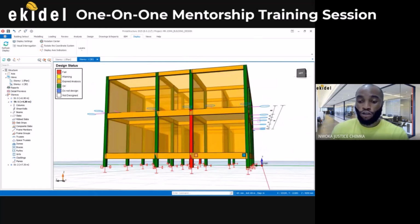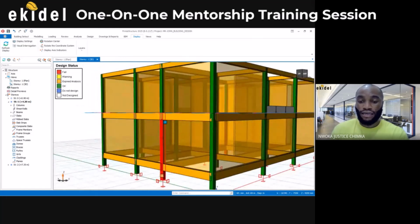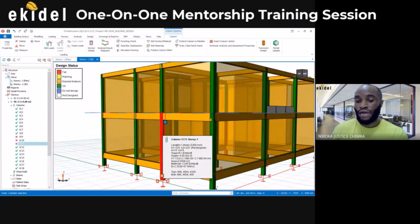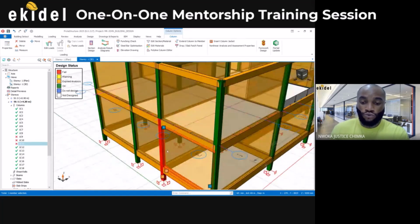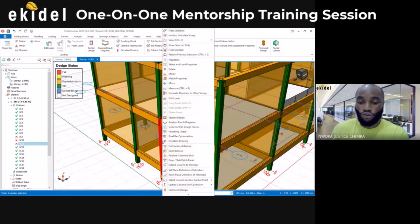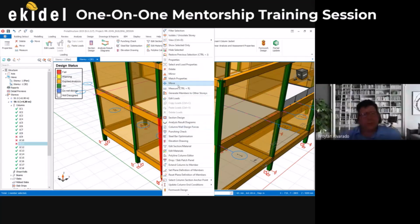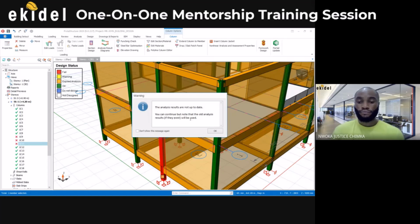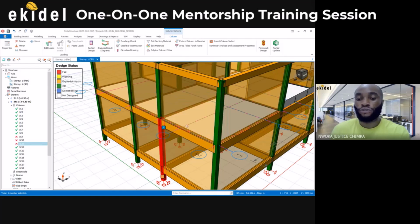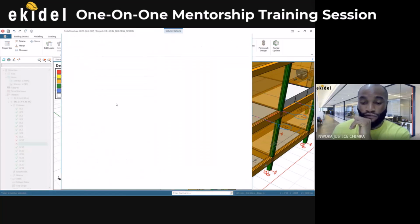But if I touch this column again and increase the size or something, then say okay, let's do it now. For the column, it's the same thing. Click on the column that is failing, right click, and then say section design. Yeah, right here. I'll just say okay, because the thing we've done is cancelled. I'll say yes, continue for now, and then it will open the interface again.